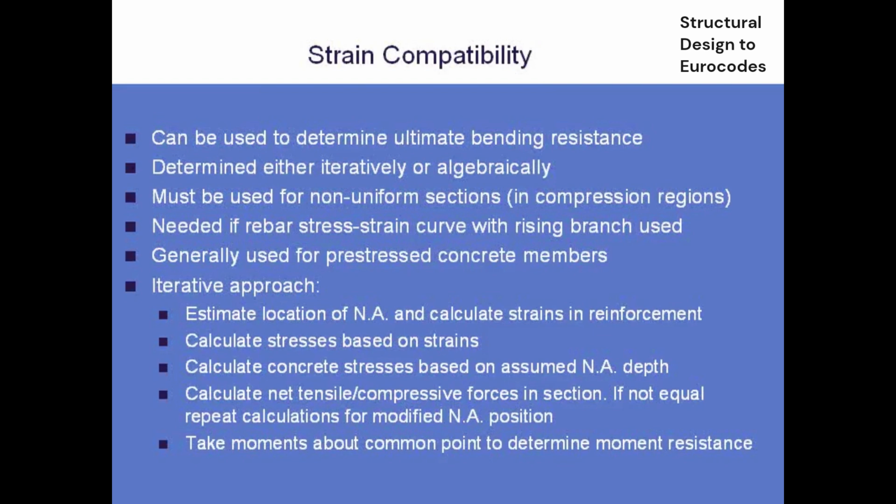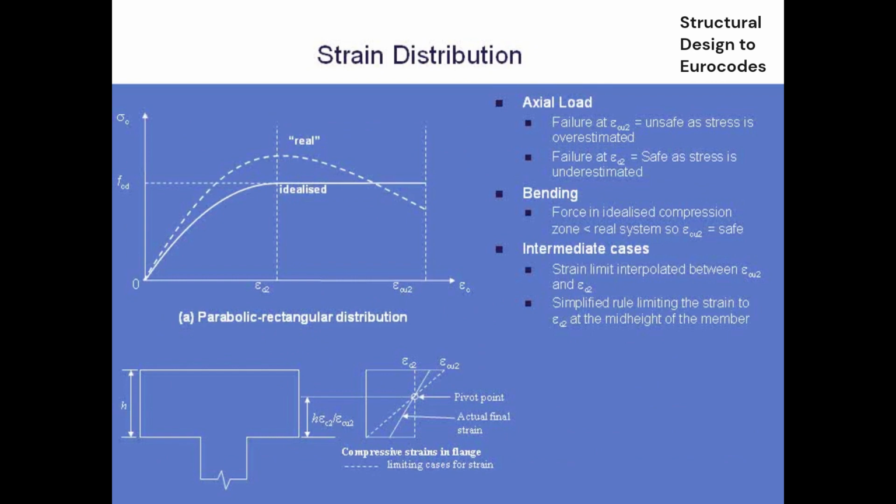So, just before I put up a simple formula, there's one other thing just to baffle you with, and then you can probably largely ignore it, having hopefully understood what it's supposed to be doing. In the clause we were just talking about that lists out the assumptions, it talks about how in some situations you may not be able to actually get to the full strain limit of epsilon cu2. Epsilon cu2, by the way, is the 3.5 millistrain, the same sort of number that we had previously in the British code, for concretes up to, I think, 50, 60. Below that it starts to drop.